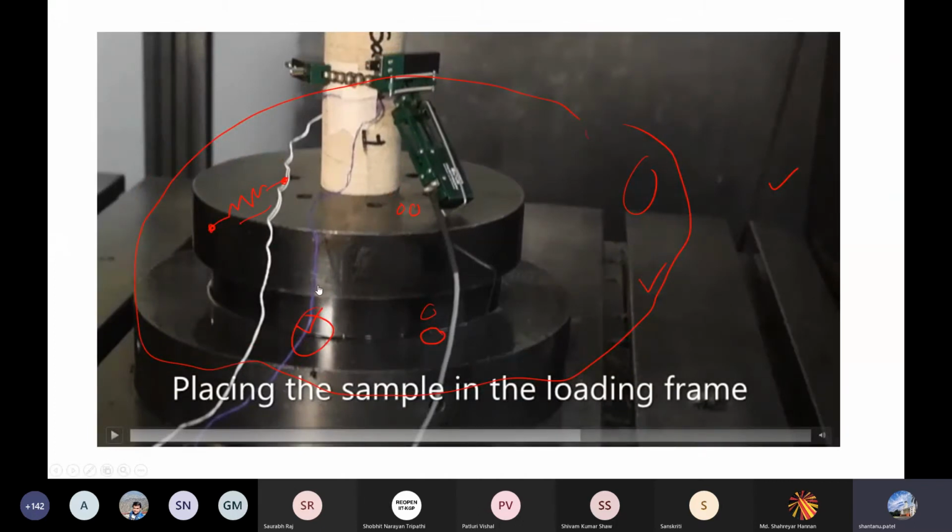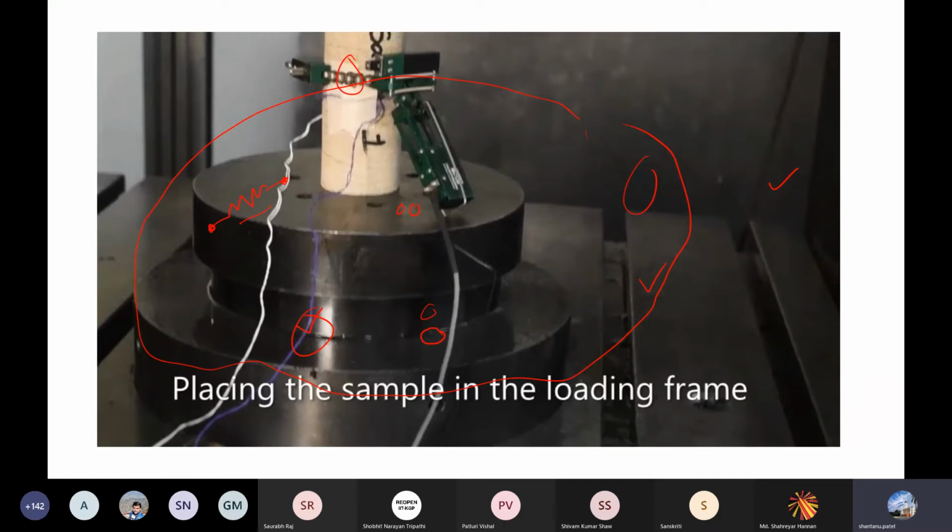And then what we do is we place this specimen under that loading frame. And if you can see here, along with the strain gauges, we have an extensometer. So this is kind of a mechanical thing, right? Like when you compress the sample from the top, you can see the chain here, right? This chain thing here. So there will be a change in length, and our data acquisition system can record the change in length, right? So and you can get the strain.